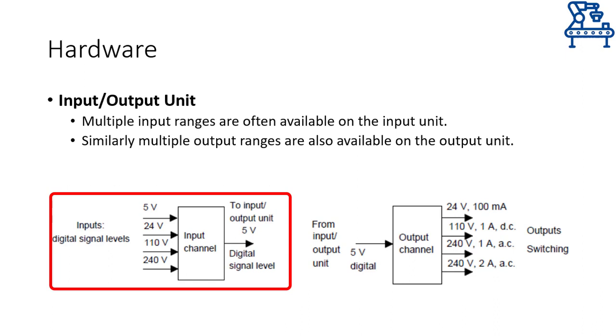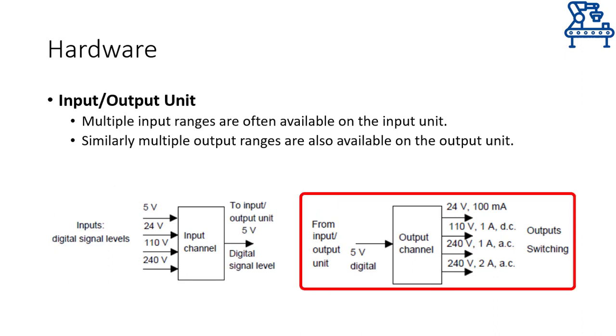The signal conditioning circuit inside these modules allows conversion from one voltage level to the voltage levels required by the PLCs. Typically, all external voltages are converted to a 5-volt digital signal, which is then provided to the processor. On the other hand, the processor generates a 5-volt control signal, which is converted to appropriate voltage levels for different output module ports. Typically, digital and analog ports are both available on output modules so that digital or analog actuators may directly be attached to the suitable port.